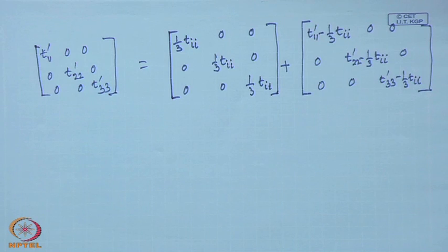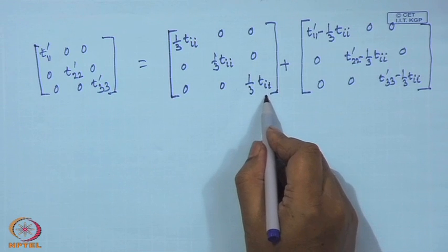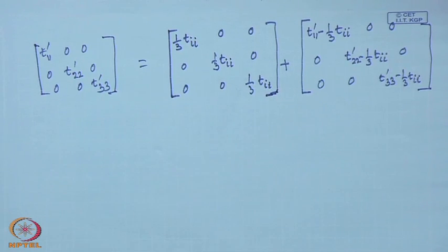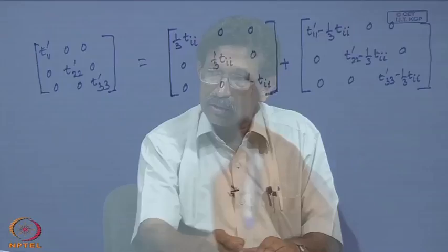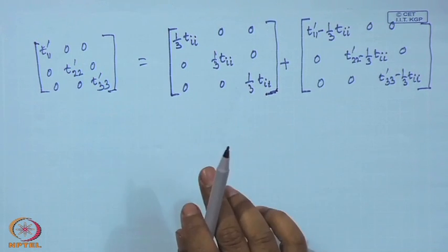Now, look at this first stress system, what it is. This is equal in all direction. This has a spherical symmetry or isotropic behavior, equal in all direction. And since all are same, this means that all three are either tension or compression. As it happens, it is actually compression. That is what fluid can take at rest. It cannot take tension. Anyway, but all three are same. Our experience says that this is compression, that all three are compression.